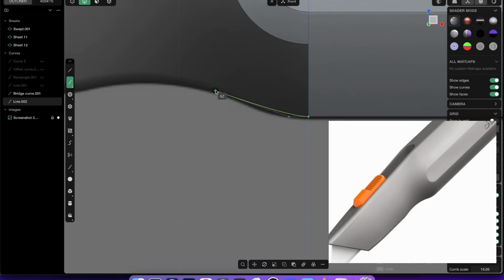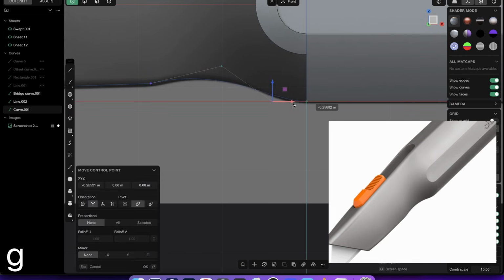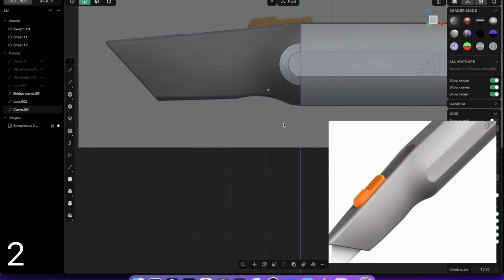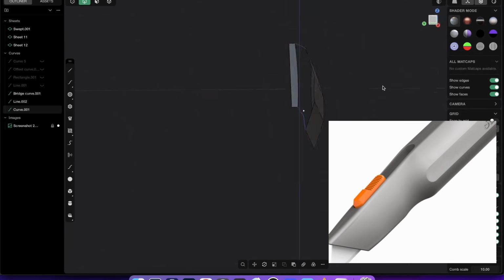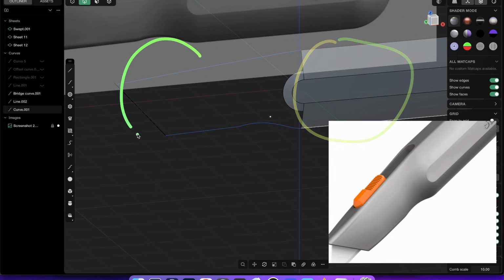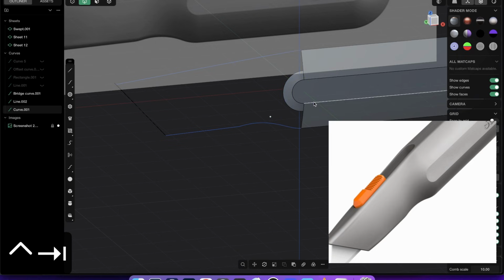So something like that. And now let's just create a simple curve. So I will create one point and then just connect here, press 1, and I will just adjust the point. And I will also select this point and with G just drag that out a little bit. So something simple like that. And that looks fine. And now let's create here a surface, because then we have on the right the surface, and then we will have on the left the surface, and then we will be able to create here a nice patch or X-snaps or whatever.